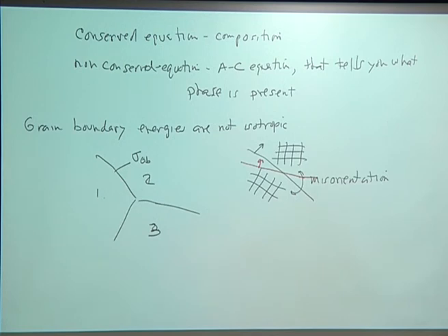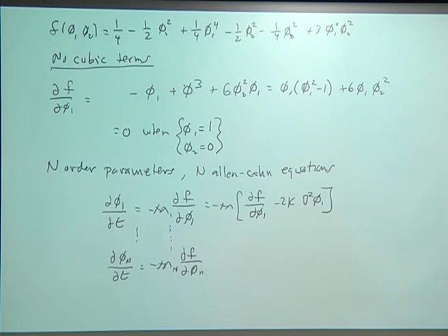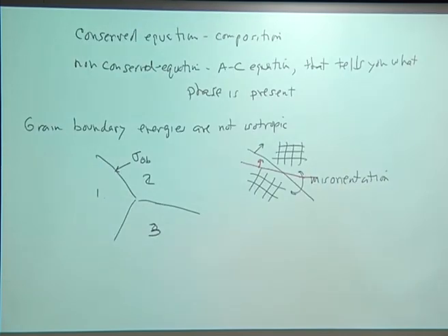And putting all of these degrees of freedom together, the 3 degrees of freedom associated with the misorientation and the 2 degrees of freedom associated with the normal, in a phase field model is still pretty challenging. It's still a really challenging thing to do in order to get the full 5 degrees of freedom of a boundary. But what people basically do is they go into this model and they change M, they play with the heights of the barriers and all that kind of stuff in order to get some anisotropy into the problem.